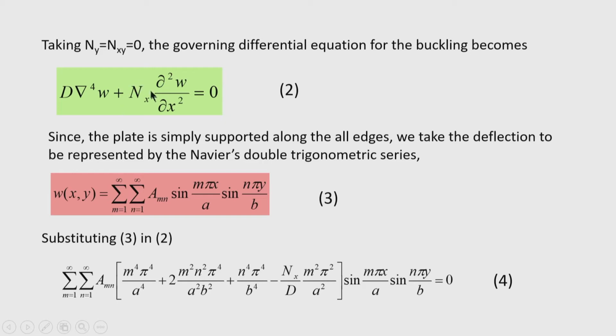Here the in-plane force is in the x direction, but in some problems the in-plane force is in the y direction, or there is a combination of in-plane forces in x and y direction as well as membrane shear forces. Then also this function can be substituted in the original differential equation and we can get a relation like that.